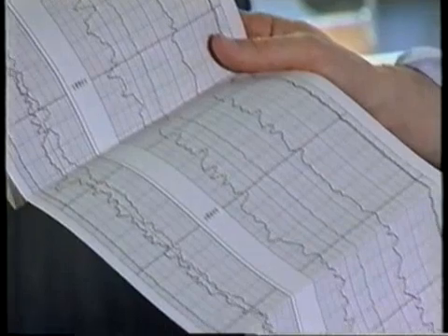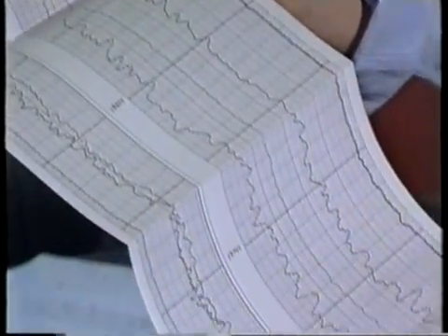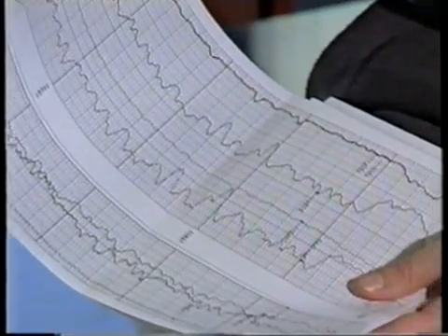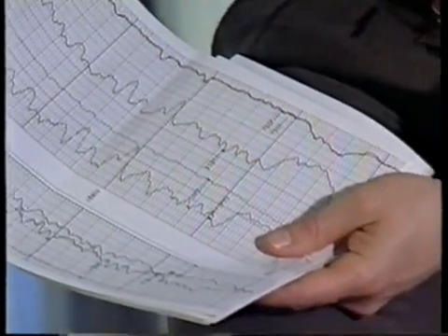All service companies show essentially the same curves in the same tracks. However, the curves of one service company cannot in general be compared directly to those of another. The spacing between the detectors is likely to be different, as is the way the electronic measuring gates are arranged. Therefore, count rates, ratios, and even sigma values may vary among service companies.